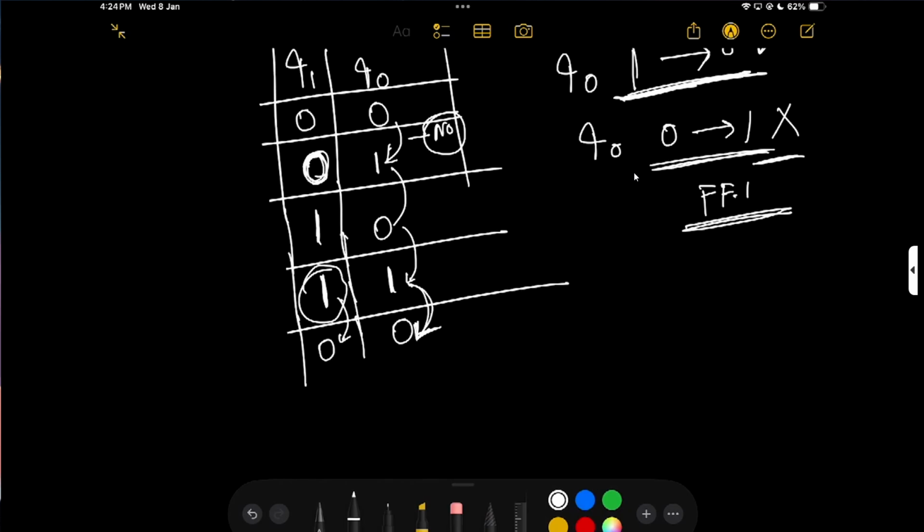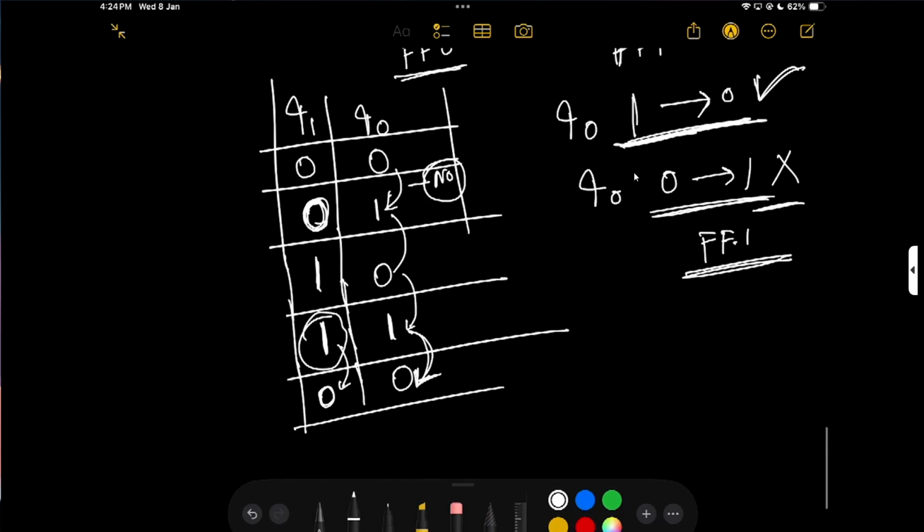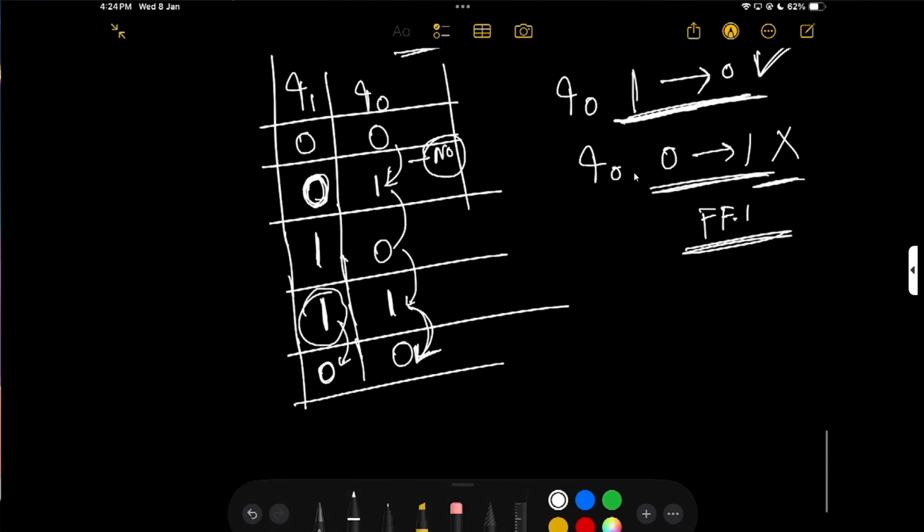And what is the previous output of q1? That is 1, and now it will be changed to 0. So we see that this is nothing but 0, 1, 2, 3, and again 0. So it is like an up counter. You can see it will increase by 1, 1, 1 like that. So it is like a 2-bit up counter.